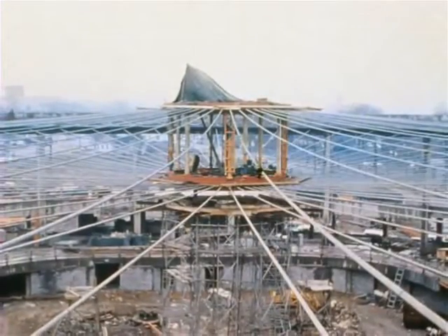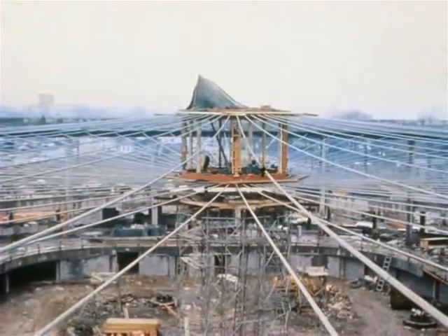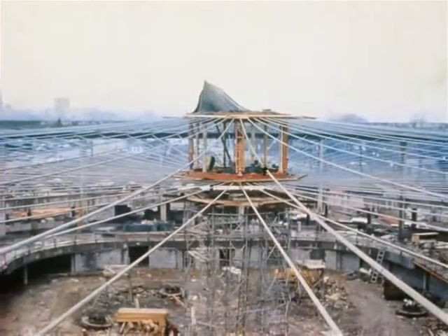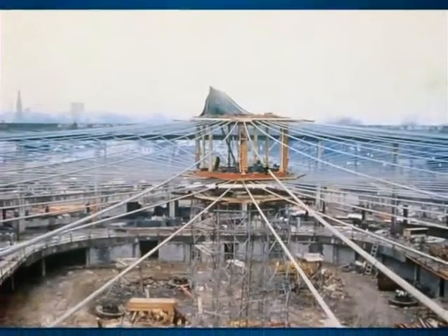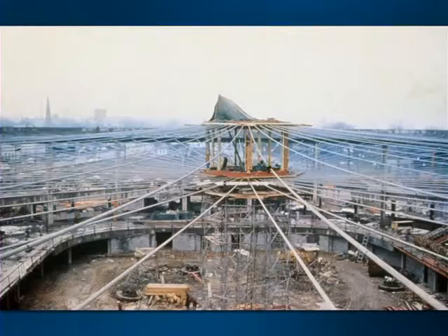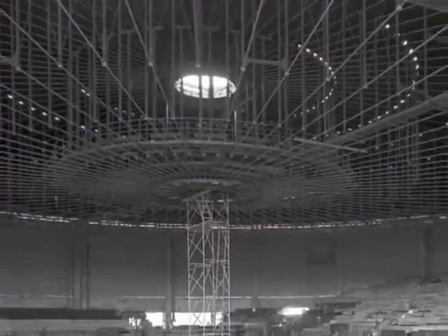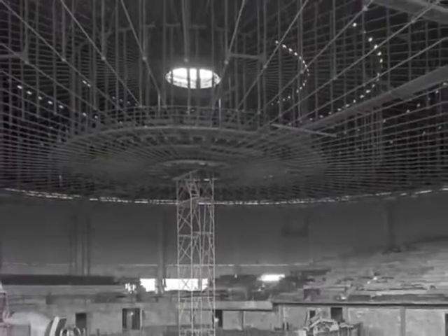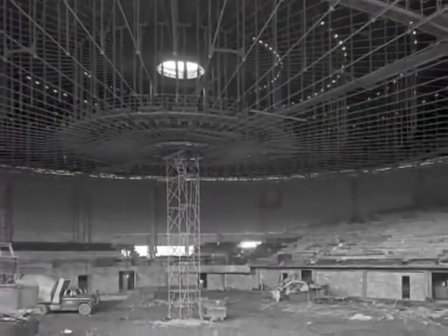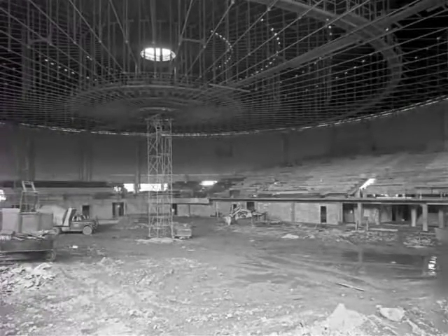So why was the Municipal Auditorium in Utica, New York, the subject of such an important structural innovation? Well, it turns out that the quality of the soil on the project site was quite poor, meaning that its load-carrying capacity was relatively low. To ensure that the building didn't overload the soil, it had to be very light. The cable-supported roof was a direct response to this situation, a wonderful example of constraint as a stimulus for innovation. This photo shows the roof under construction, and as you can see, it is very light indeed.